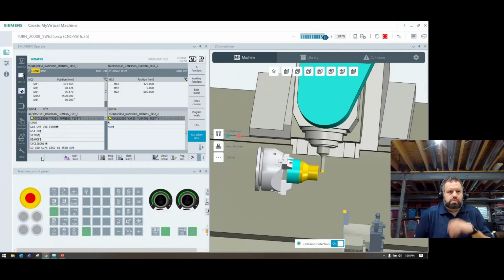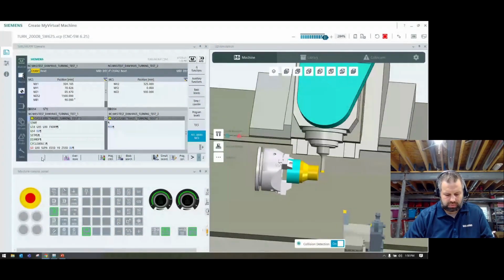So that's the only thing I think. If you have a machine from an OEM and you're looking to put in one of those electronic ones where it doesn't require the spindle to be spinning, just make sure you can do a controlled feed move, a G94, feed per minute move with the spindle in M5 or not spinning. That's about the only thing I think would mess you up. Other than that, there's no reason why we shouldn't be able to support them natively.